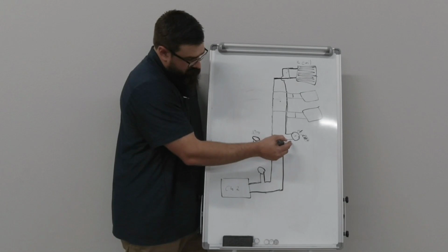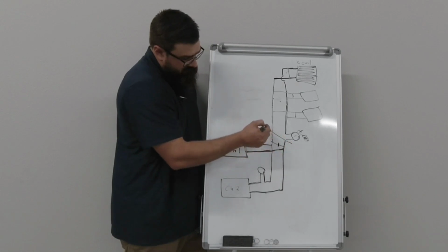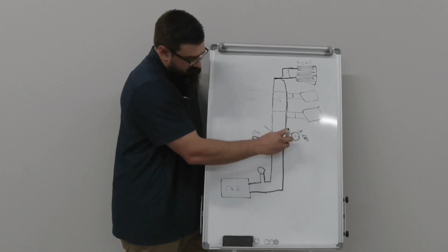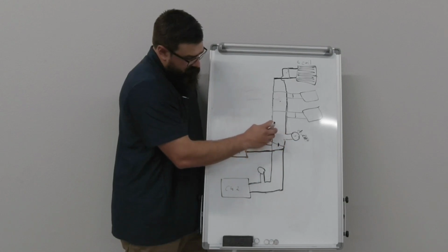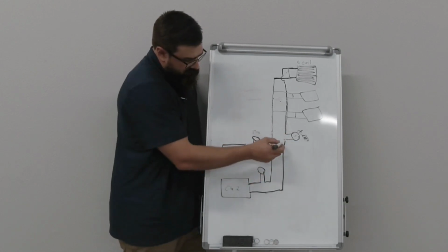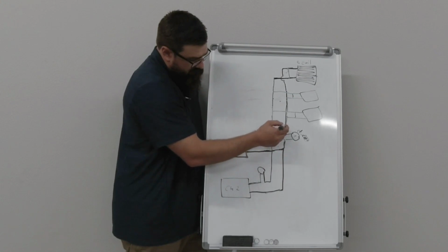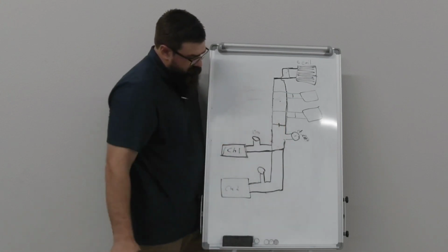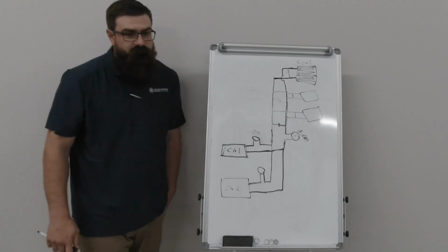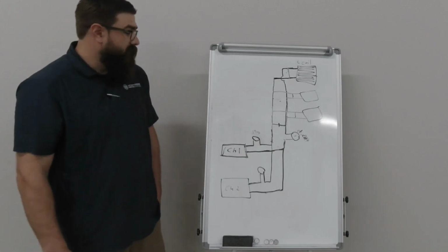Because if it's not balanced properly, you end up overfeeding water back to the entering side of the chiller, making it too cold. And that chiller is going to buck you for it. It's not going to like that, which is going to cause the whole building to have issues at that point. Yeah, and you have issues with your chillers too.